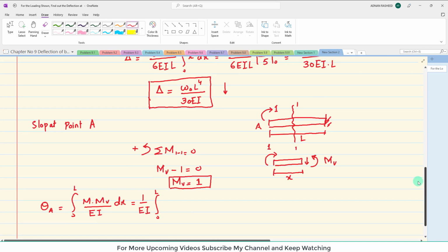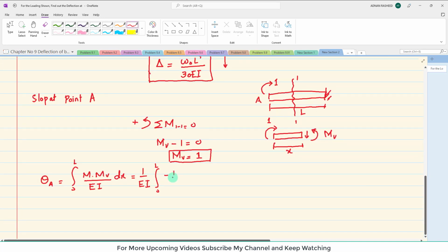Clear? So it is minus 1 over 6L W naught into x cube, and MV is 1. When you multiply these two, it will be 1 over EI into integral of minus W naught x cube over 6L into dx, and the limit will be from 0 to L.